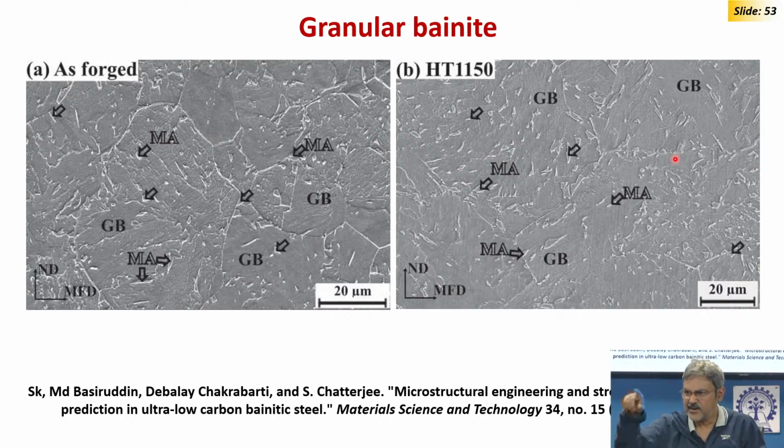So, a granular bainite-like structure with small MA islands is called granular bainite, but if you do EBSD, you will be able to find the low angle boundaries which are separating the platelets. In optical microscopy we cannot. It is not good for toughness because it is a coarse structure.